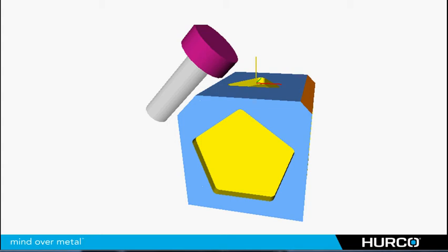Okay, this time I want to cut a chamfer on the other side of the part using the side of the 1-inch end mill. I'm going to put a 1-inch chamfer down that left side of the block. Notice that the tool is going to tilt in the same direction as it did on the other side. I'm still going to tilt the tool in a positive 45 degrees.